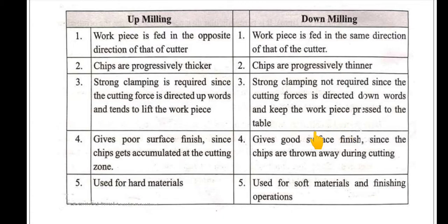Okay, next, in up milling we get a poor surface finish. Since the chips get accumulated in the cutting zone during the up milling process, the surface we get will be rough, or a poor surface finish.